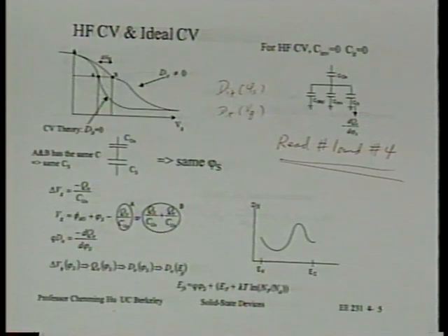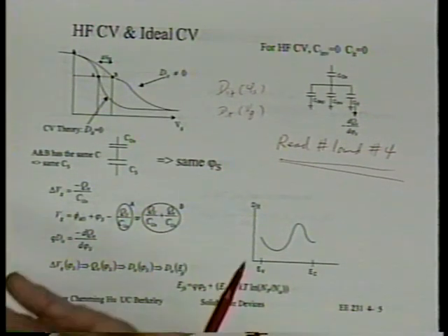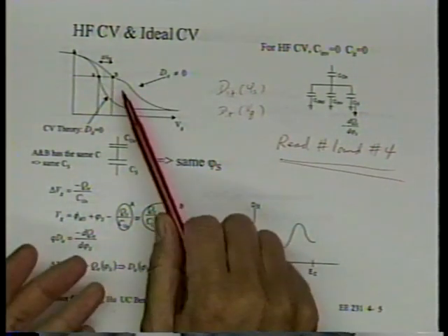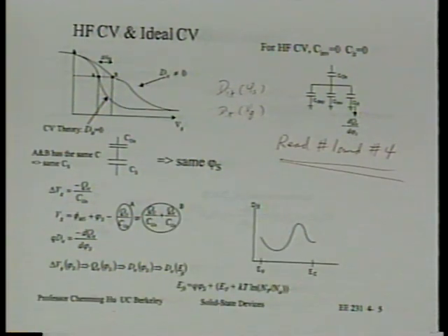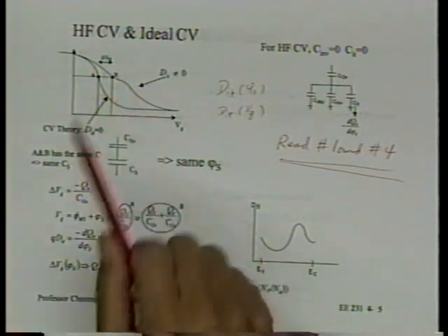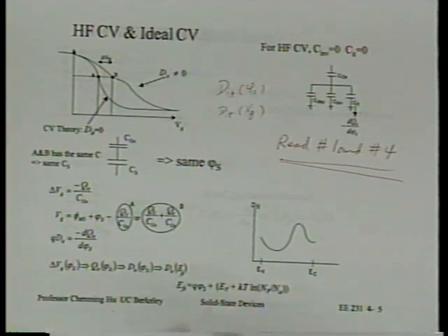And as I said, anytime you have a new dielectric technology, you probably shouldn't be surprised to see a CV curve like that. Or if you take a good MOS capacitor but apply electrical stress on it for a while, you shouldn't be surprised that the CV looks like that. All right, so now we're going to try to get some useful information out of the CV.